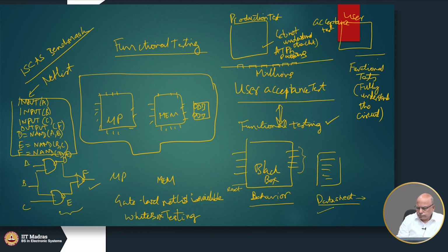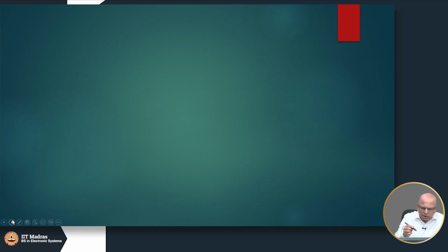Okay. And most ATPG today works only on gate level circuits, right. They do not work on, let us say, bigger modules like registers, adders, multipliers, etc. Okay. There has been some research on these topics, right, but in practice people continue to use gate level netlists when they are generating tests. Okay. All right. So, let us go back to sequential testing.